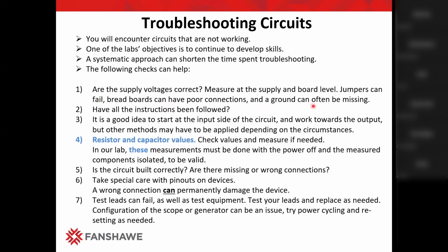So this is all part of checking the obvious. Yes, it should be there. Does it work? It should. I know it should, but does it? Check and double check. A lot of problems actually require just that: checking the obvious. Oh, something is not there. It should be there. It looks like it's there, but it's not. So breadboards can have poor connections, and ground can often be missing. All right, so that's part of the check.